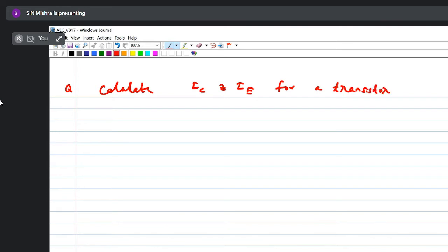So with the help of one circulator and one fiber Bragg grating, you could drop one wavelength. Similarly, for the next ones you will use another circulator and another fiber Bragg grating for a particular wavelength that will be dropped. Now you are left with 2, so you will get another one.